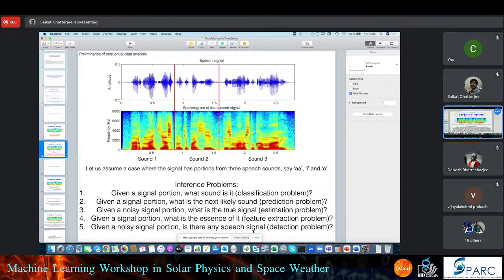If you assume there is a true signal and then use the noisy signal for some inference task, you are actually doing wrong things, right? Because the signal does not even exist there. So you must know whether a true signal exists. This is detection of the true signal. Actually, in your phone, this is called the voice activity detector, VAD in our terminology.